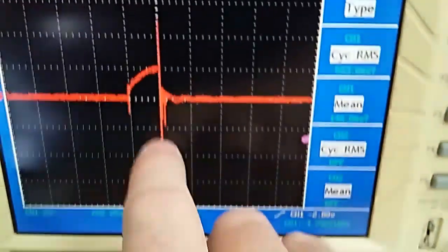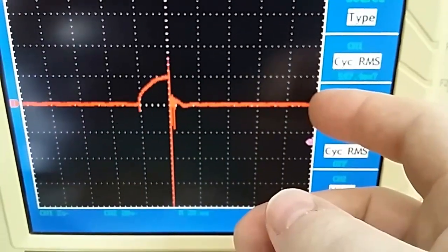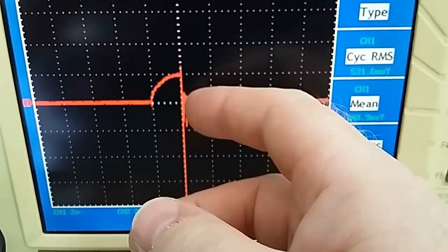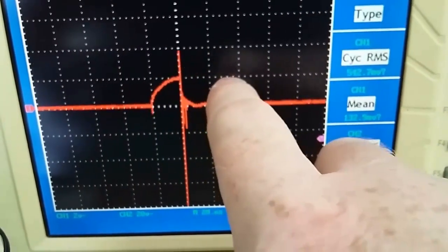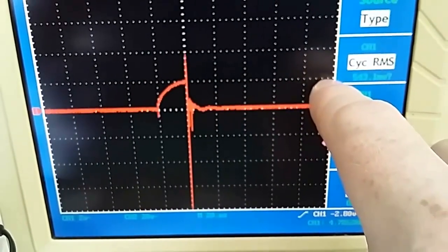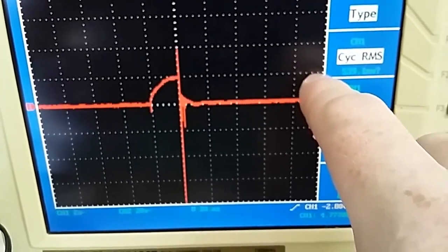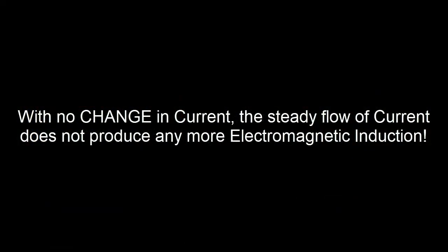What we've done on our input coil is we've wound it back, so instead of a 25% duty cycle, it's now a 5% duty cycle. So what we had before, with all that extra current running through the top here, that current was supporting the current on the secondary coil for a longer time frame.